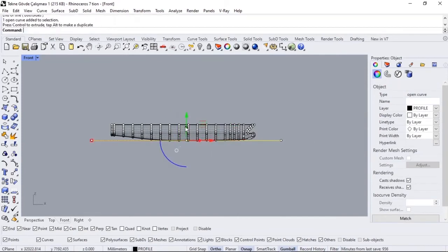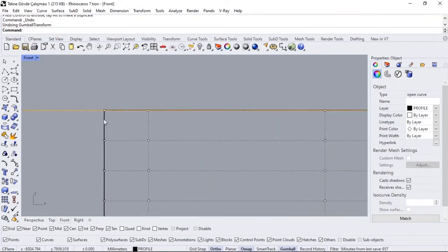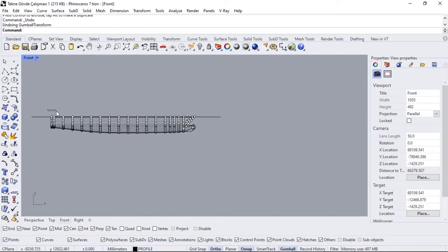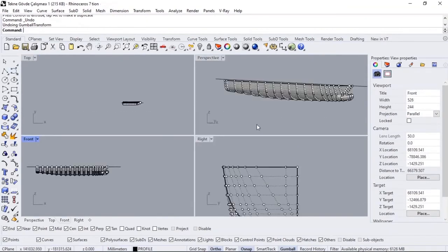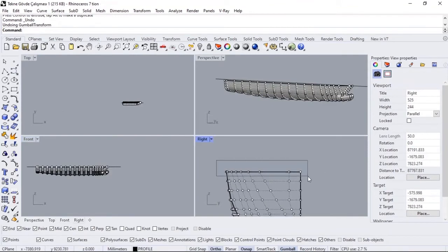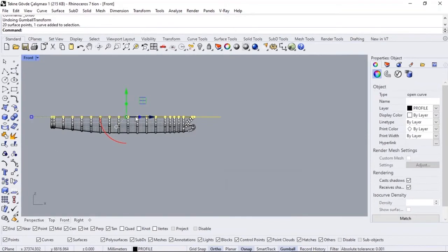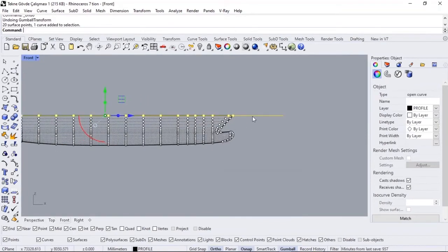Then I click the green arrow and I write 8.2 meters and enter. I had to write 8.2 meters, that is 8,200. We are in millimeters. I write 8,200, then let's select all the control points. We can do this more comfortably in right view. I select all control points and again, front. I deselect the line by clicking the Control key.